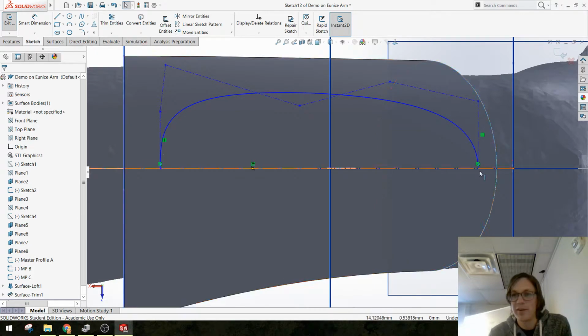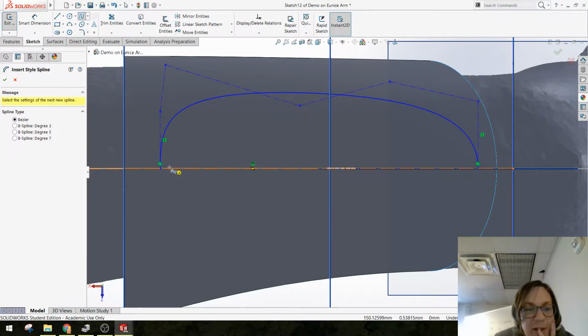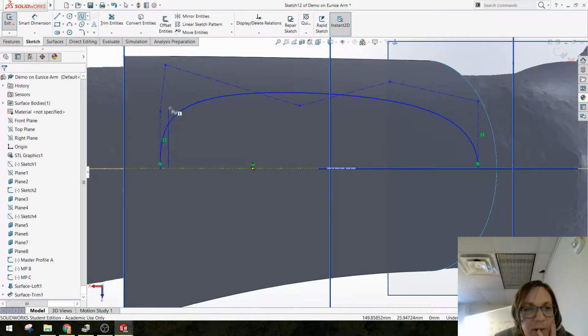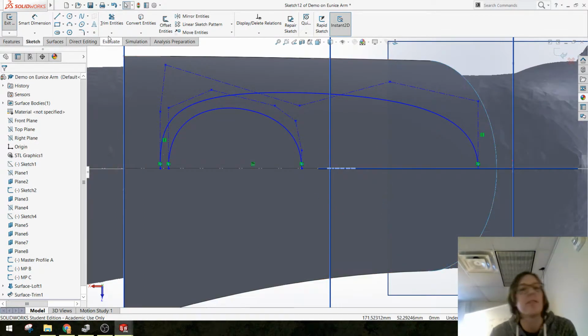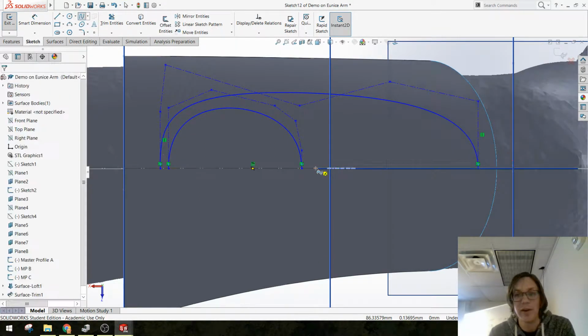So this, I'm guessing, is what I'm going to use for the padded area. I'm going to do a couple more shapes on my master sketch here that are roughly offsets of this shape that I'm going to use to make some articulated pad shapes. And this is where, if you have a sketch of the bottom view of whatever it is you're trying to design, it will come in helpful because you're not guessing at shapes anymore.